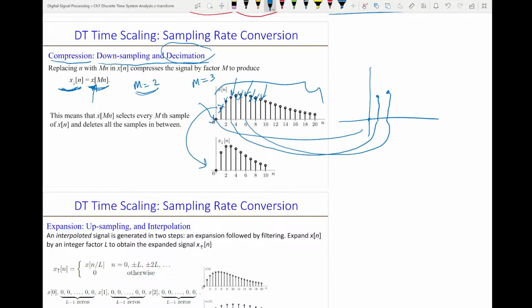If I have this signal, for example, that was a continuous signal and the bandwidth was 20,000 hertz and the sampling rate was 40,000 samples per second. Now, if I downsample this discrete signal further down by a factor of 2, it's like I took a sampling of this rate, 20,000. Now, aliasing will happen. The bandwidth here is 20,000 and I'm sampling not twice it, exactly the same.